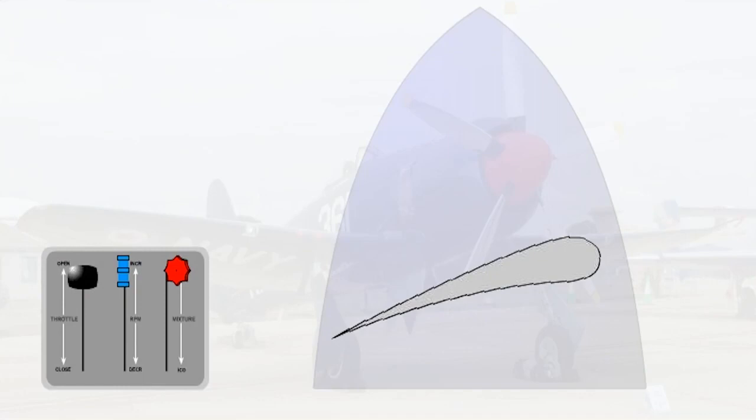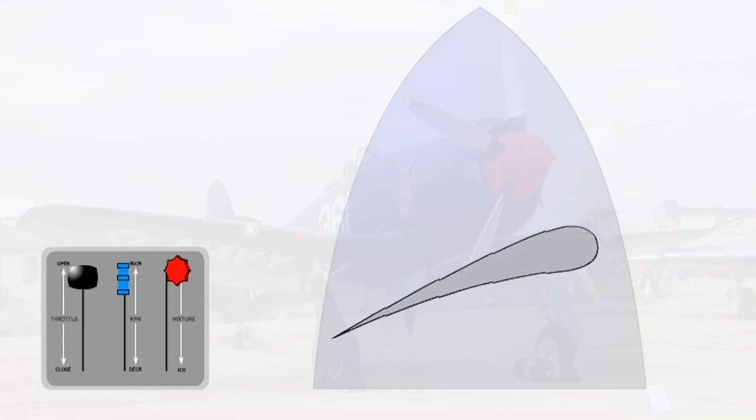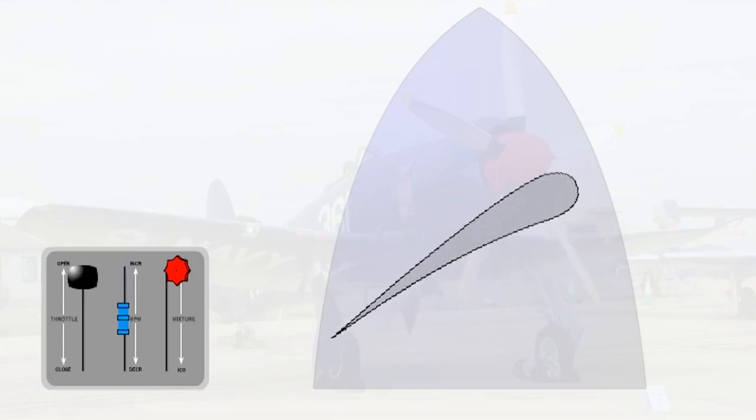This diagram illustrates a typical set of engine and propeller controls for a small piston engine aircraft with a variable pitch propeller. Throttle, propeller, and mixture are shown in the takeoff, all-forward position. For a given throttle setting, pulling back on the propeller control will decrease RPM by coarsening the pitch of the blade. Conversely, pushing forward on the propeller control will increase RPM by fining off the pitch of the blade. Once RPM has been set, it will be maintained within the operating range of the throttle lever.